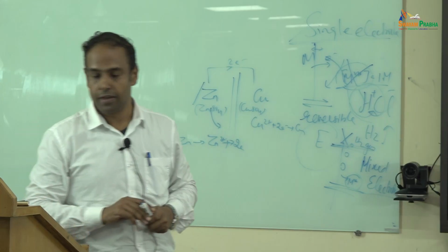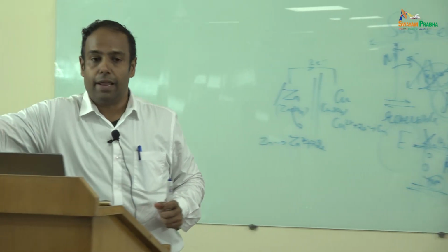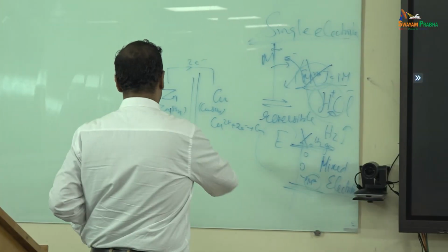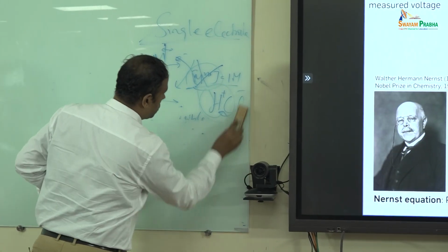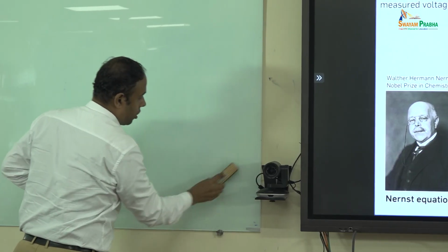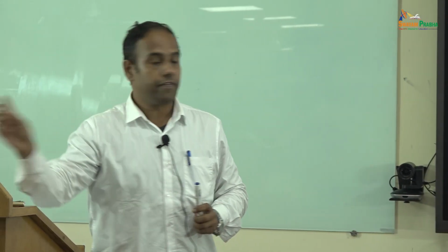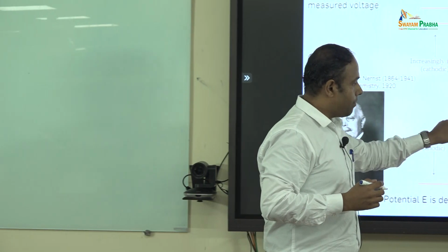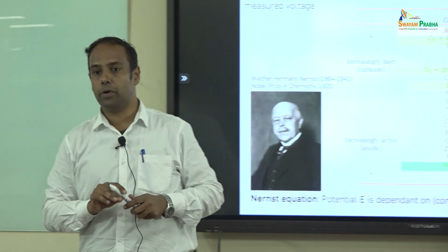Now, this is actually the basis of ranking the elements in terms of their reactivity, which is nothing but your E, given in terms of delta G. So you move from the top to the bottom, and you are going to see that the nobler elements are arranged at the top and more active elements are arranged at the bottom, right. So if I can get a comparative behavior, I normally protect iron by coating it with zinc, which is called galvanization. So, how does zinc prevent iron from corroding?